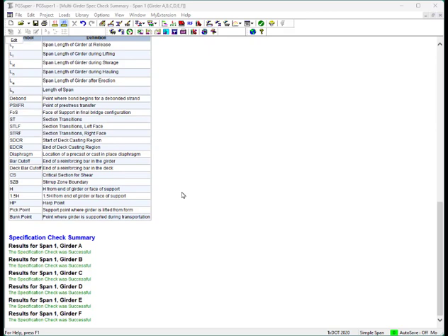One last note about our design here. As you recall, I made a last-minute change to super elevations, and it almost derailed our girder design. So I think it's really important to know that you should input accurate bridge geometry unless you're just doing a very preliminary design. Otherwise, you may run into trouble like we did. And luckily, we were able to get the girder to work in all locations.